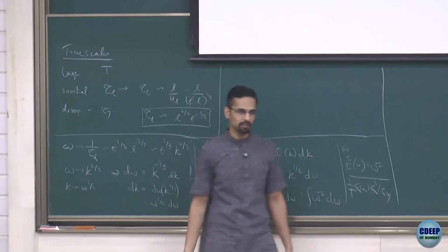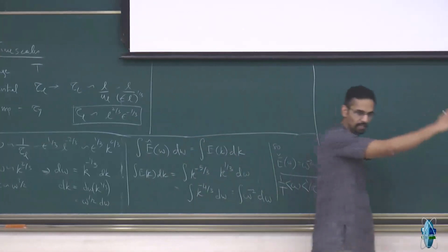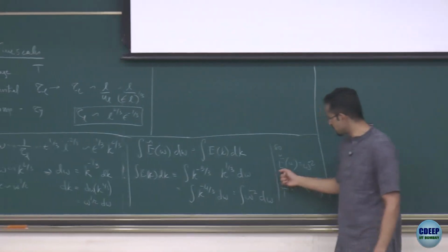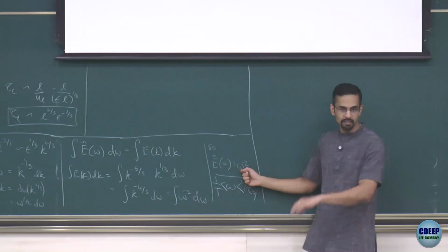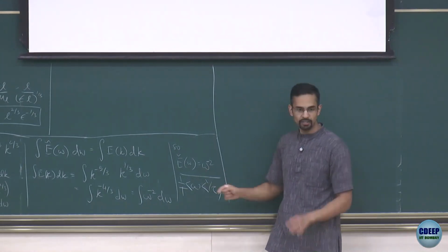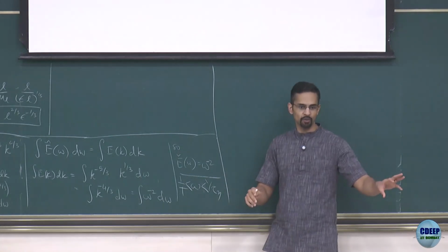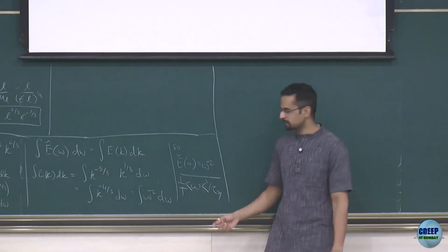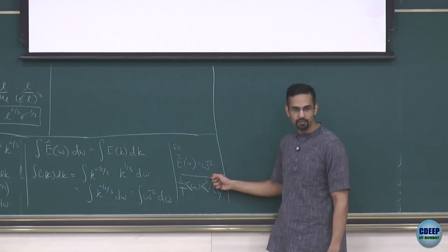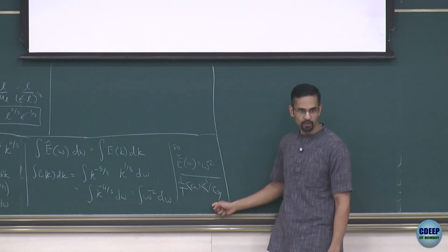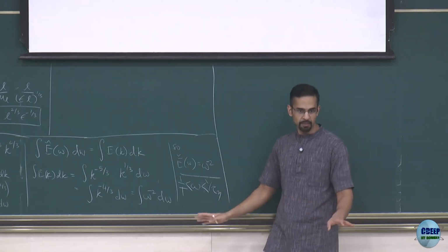It's all chaotic. But there are some variations happening on large time scales, and on smaller time scales, and on smaller time scales, and so on, in a hierarchical fashion, such that in fact you get a power law distribution of spectral content in all those different frequencies. So you cannot just split up turbulence into some slow oscillations and some fast oscillations. They're all possible frequencies inside. But then at some large enough frequency, I will hit the 1 over Kolmogorov time, and then I will have the same behavior.